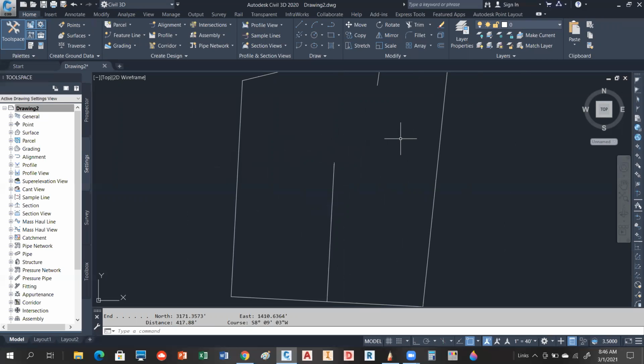So we have a delta of 30 degrees that is given, a length of 104 something, but the radius is 200. Now if you notice, the distances that are really pure there is the angle is 30 degrees explicit and the radius is 200. So I would probably rather use one of those as opposed to, say, that length. That 104.72 is probably rounded.